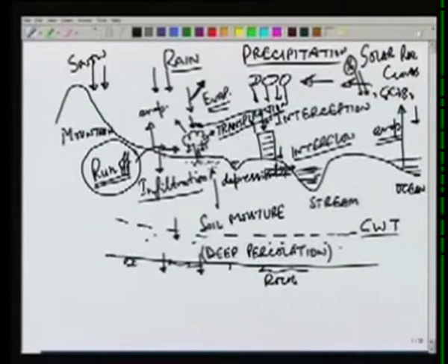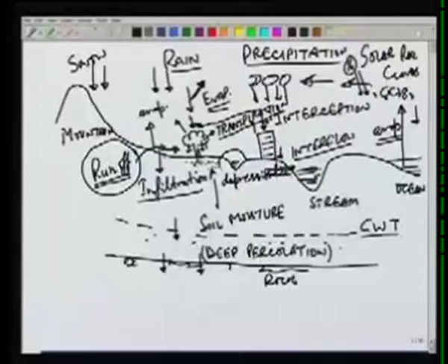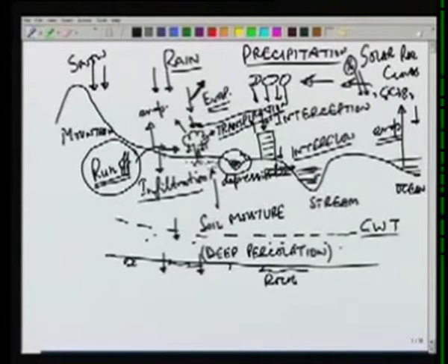And depending on how fast or how slow it appears, it may be a delayed appearance on the surface, or it may come very fast. The depressions on the ground surface will also store some of the precipitation. So before the runoff can start, we should have some storage in the depression, and that is also counted towards losses. So once we have precipitation, we will have some depression storage, and once we fulfill all these depression storage requirements, then there will be runoff over the surface and going to the streams.